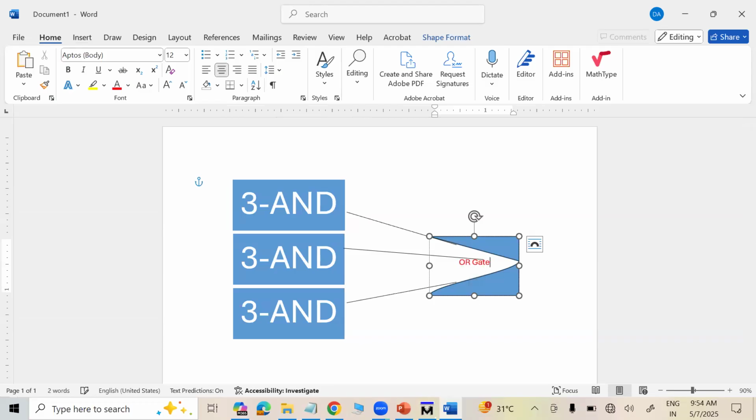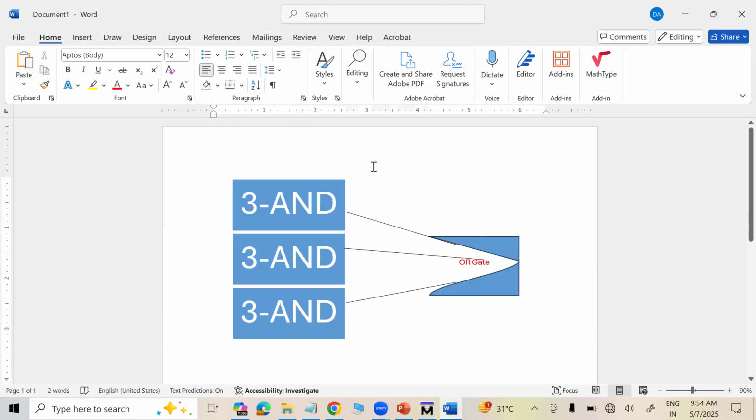This is the OR gate. Now, suppose you want to have this circuit, how will it be done in VHDL? A similar circuit is repeating itself. Means the same logic is repeated 3 times here. So it is logical to write the three input AND gate function one time, and then you have to call the same function 3 times. The outputs of these gates should act as input to a 3 input OR gate.